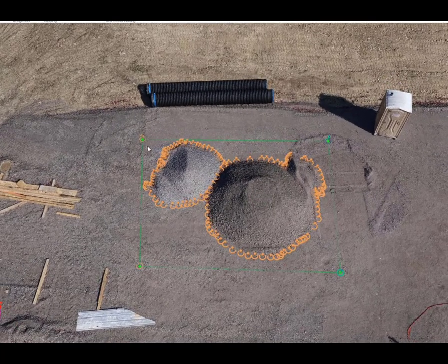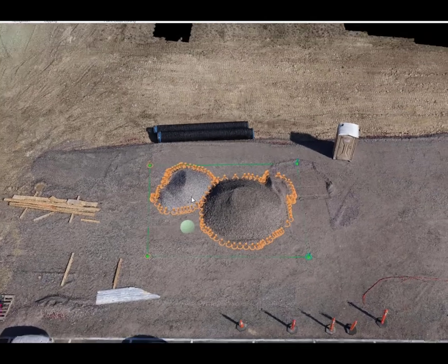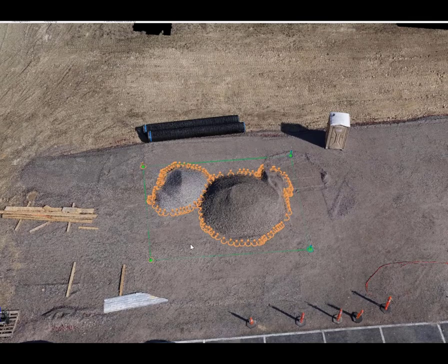To follow up on that, we processed the imagery again with no GCPs. We just put in these 4 distances as what Pix4D calls scale constraints. We did the volumes of the small pile, large pile, and the composite, and compared those for consistency, which again was about the same. There was no significant difference between the volumes, whether we used GCPs or scale constraints. So the scale constraint seems to be a viable method.